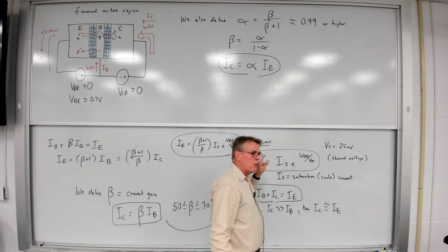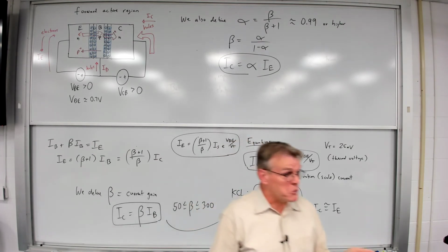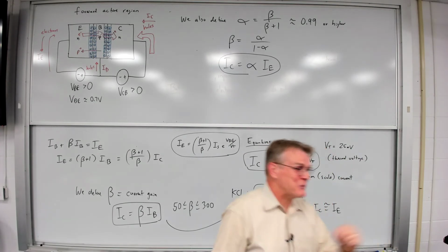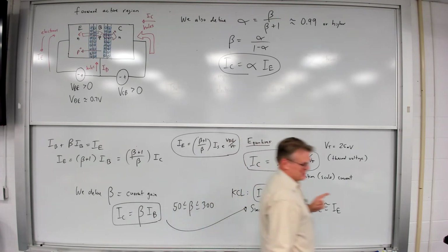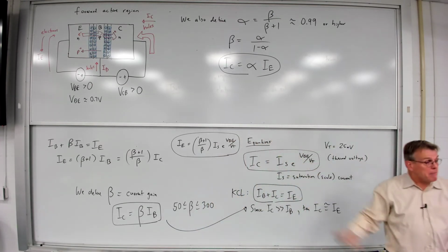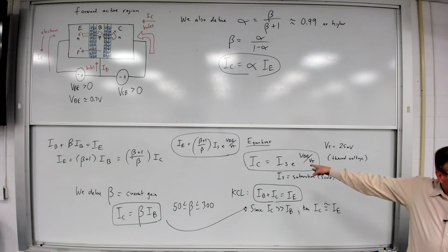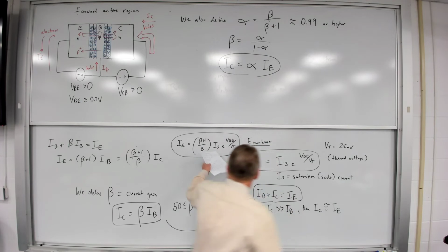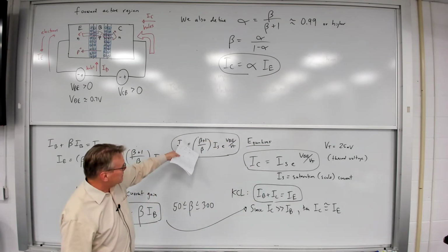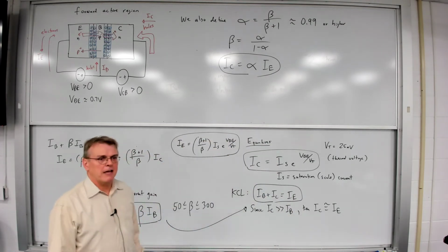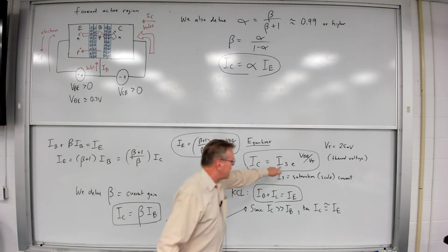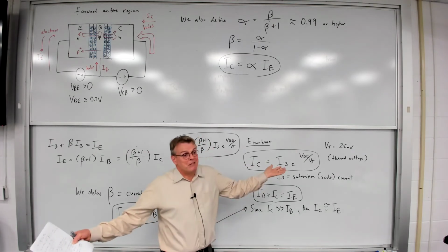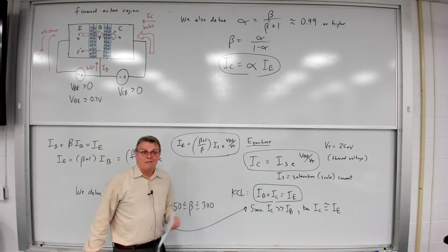If you want to learn where that equation comes from, in fact, if you want to learn how to derive that equation from first principles, there are much better professors to take this stuff from than me. Okay? I'm a circuit designer. I'm not a semiconductor physicist. So I will, right off the bat, plead ignorance as to why this particular equation has IC instead of IE, beyond the fact that as long as I define IS as beta plus 1 over beta times IS, I can write it that way. So it all depends upon what you define your scale current as, whether you want to add this multiplier or not. That's really what it comes down to. All right?